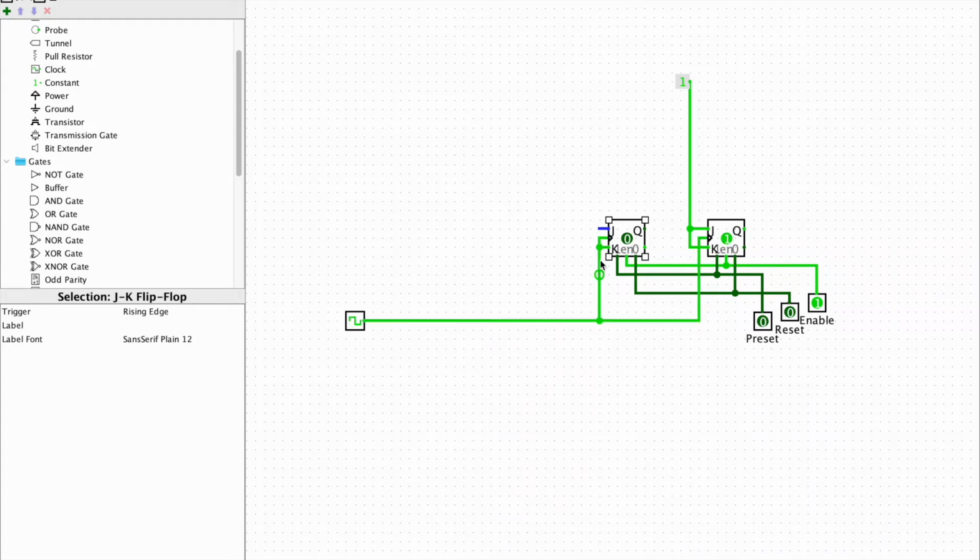That is the least significant bit. Let me call this one Q0. So whenever the value of Q0 is equal to 1, we will be having a change in the second bit. So for that, we want J and K to be 1 when Q is 1. We can do that simply by connecting it directly. Let me do this by connecting it directly.